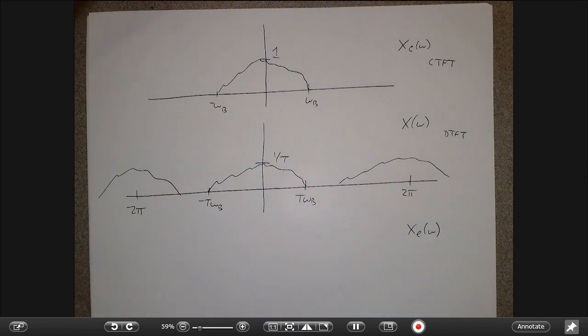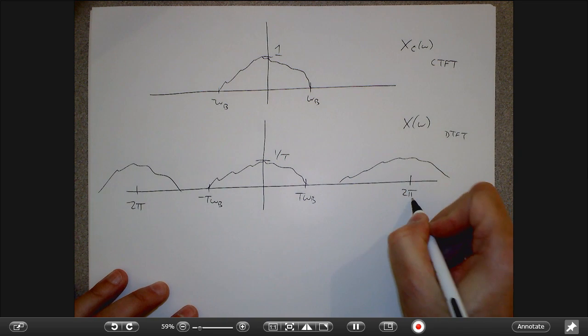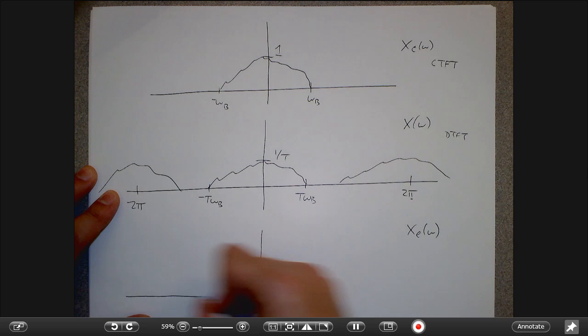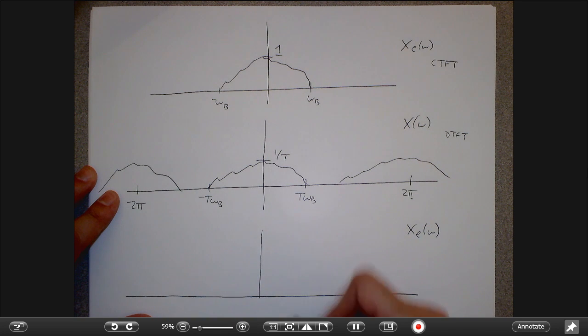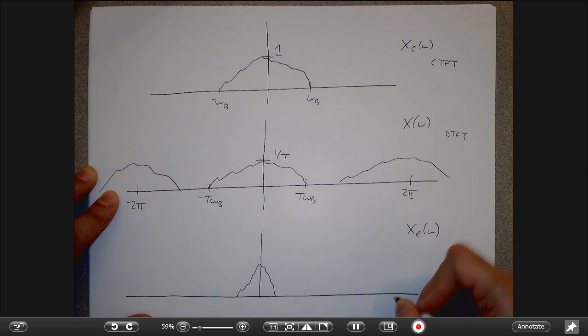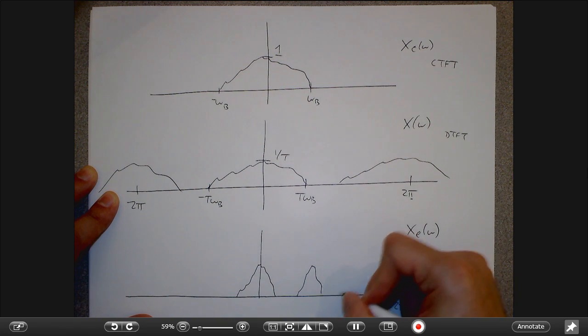That's telling me take this thing and squish the frequency axis by a factor of L. So I can see that by inserting the zeros, there's no way that I can get any sort of aliasing, because all I'm doing is taking this whole thing and squeezing it down. So what used to be 2 pi becomes 2 pi over L. So now what I get is a squished copy. Say I do it by a factor of 3.